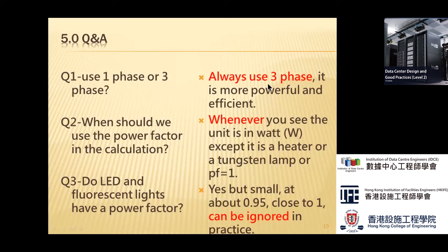Number 2, when should we use the power factor in the calculation, right? Whenever you see the unit is in watt, W, except if it is a heater or heater-related lamp, then the power factor equals 1. Otherwise, you assume power factor equals 0.8 or 0.9, or better still, we find out from the catalog, right? What's the power factor in the catalog?